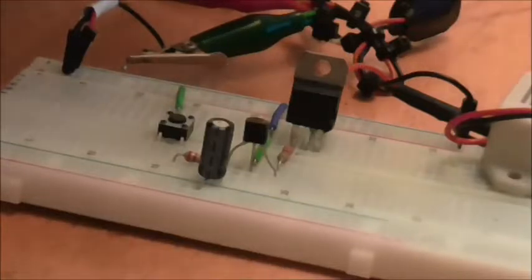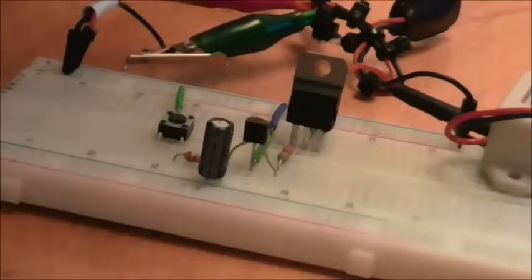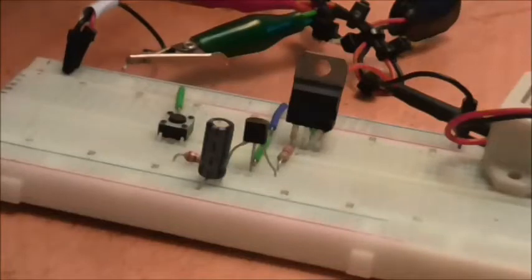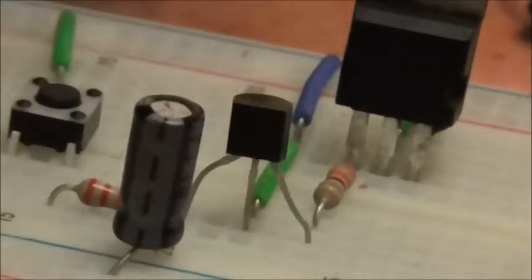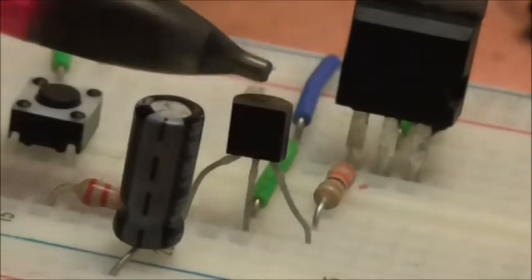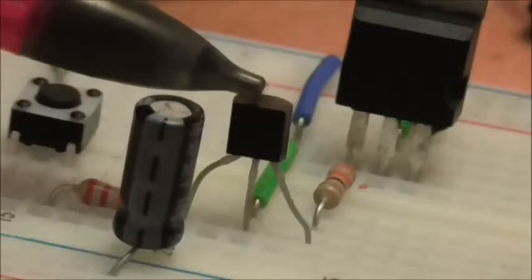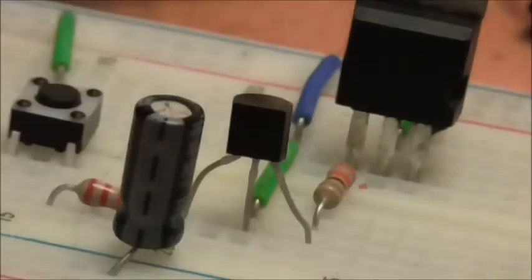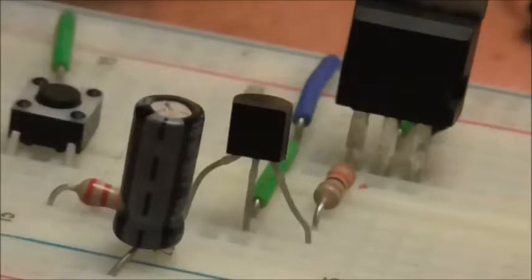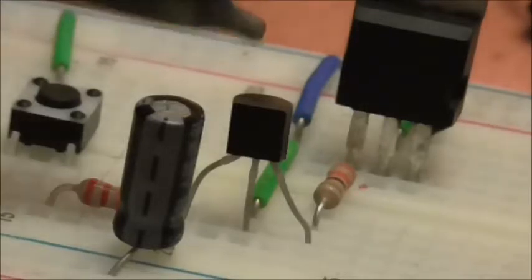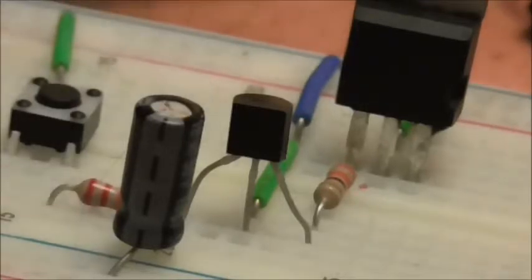And what we have here is the circuit that we saw on the simulator made manifest on breadboard, and if we zoom in a little bit we can see the parts that we've added. So, most importantly is a CP106D thyristor, which is this little black device here, and from the switch there's now a 22k resistor which is put there so as not to give the thyristor too much of a shock, and that goes to the gate of the thyristor.